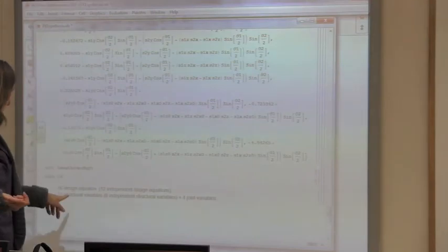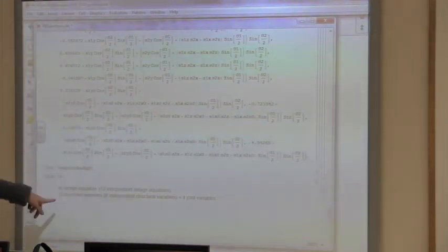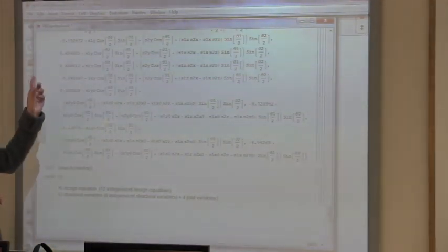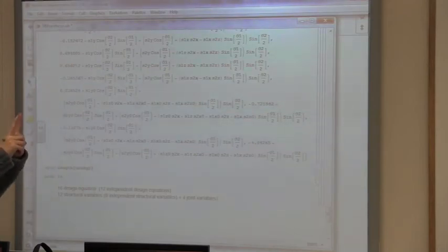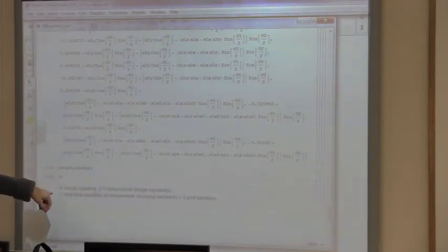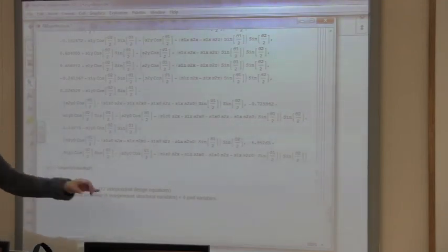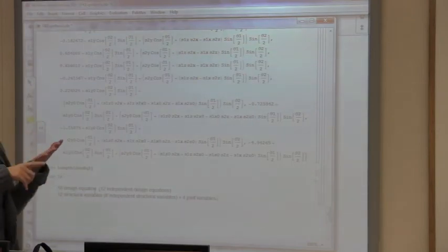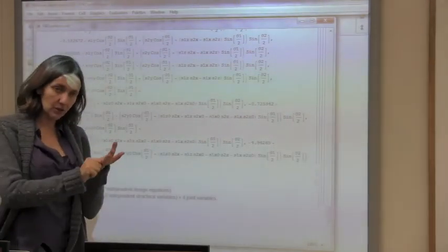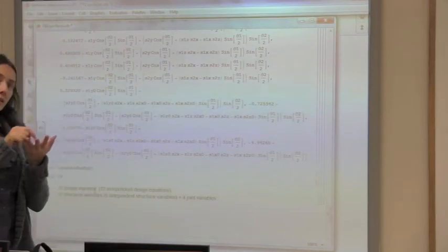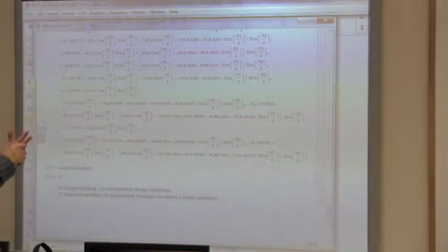For links, for the joint axis, we have 6 for the first axis, 6 for the second axis. Those never change because you move from the reference configuration to the second to the third. Okay, so that's 12, but only 4 of them are independent because the Plücker coordinates you have to constrain, right? One, the direction is unit. Second, the direction times the moment equals 0.